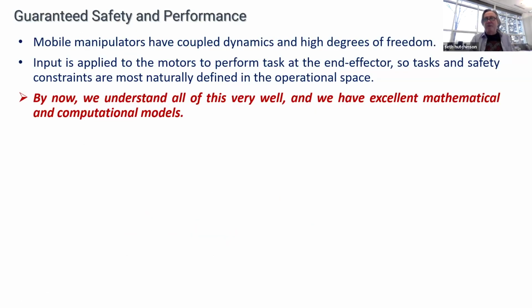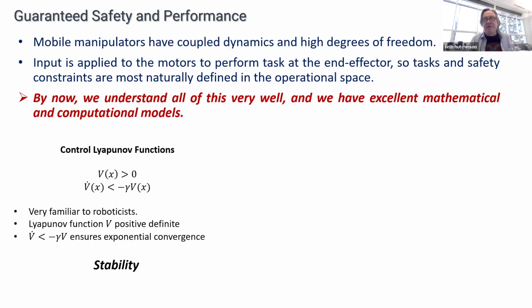What do I want to say about this? The robot that you just saw is a KUKA robot, and we know everything there is to know, right? We know the dynamics of that robot. The kinematic parameters are well known. The inertial parameters are known to KUKA, so you have to estimate them yourself if you're in your own lab, but you can.